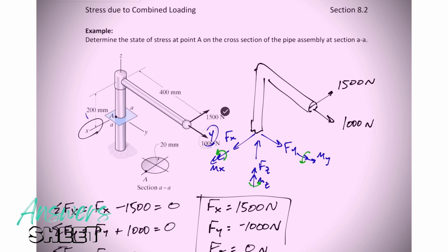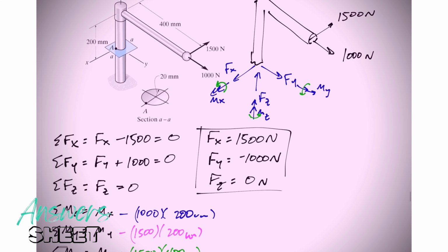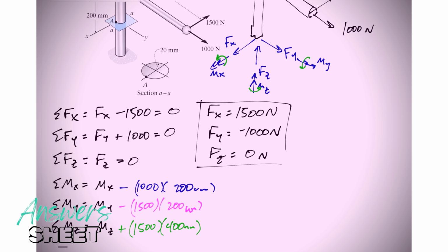So if this 1,000 Newton force was back here behind the YZ plane or in front of the YZ plane, then it could have created a Z moment, but it isn't. It is right on. There's no moment arm in the X direction, so that force only creates one moment. Okay, so there we go. Those were all the forces creating all the moments that we could find.